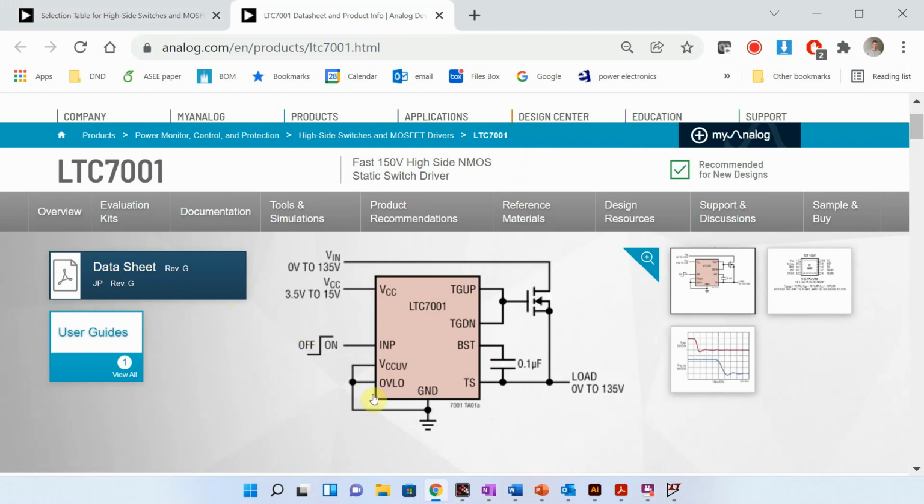So you see in this data sheet that we're going to ground all of these. We're going to put a capacitor between these 2 points. And then these 2 points are going to drive the high side, the gate of my high side transistor. And you see they're using an NMOS here. So we're going to go ahead and grab an NMOS. So this one is going to do our boosting. And so you see we have 2 voltage sources. This is the one that it's getting the boosting. And this is my supply that goes into the transistor.